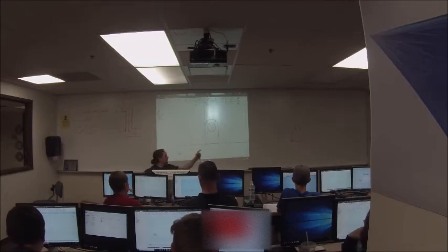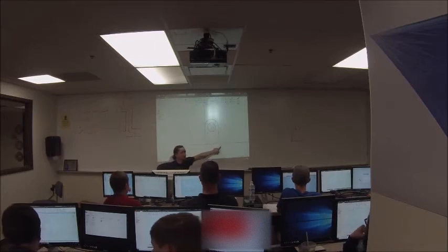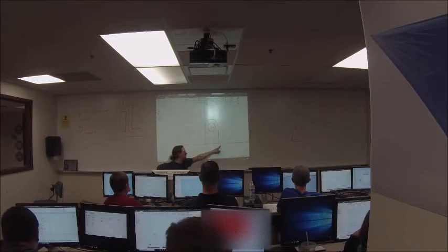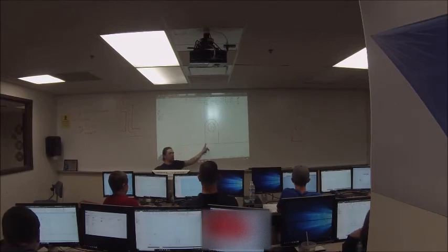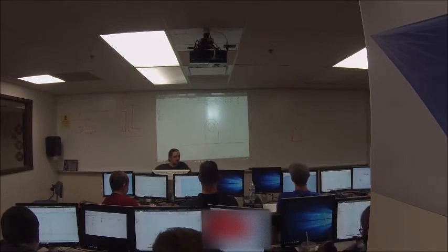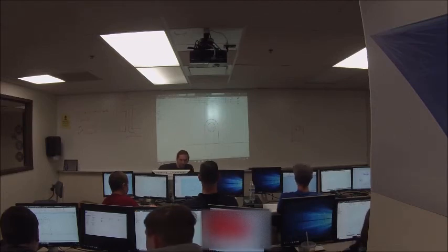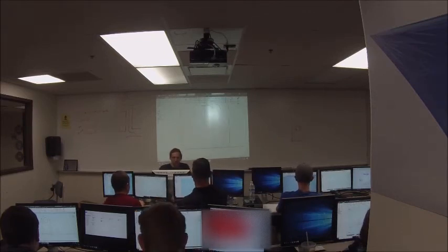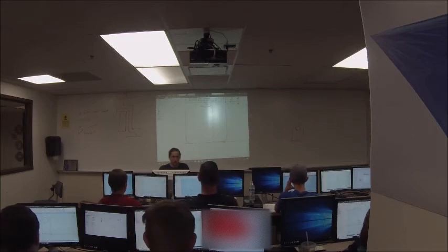Now you'll notice I'm changing one dimension, and the other fillet is changing size. Now, if you hit F8 on your keyboard, you'll notice there's a little equal sign.